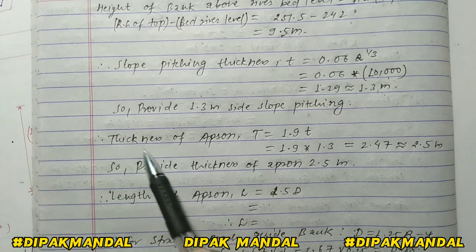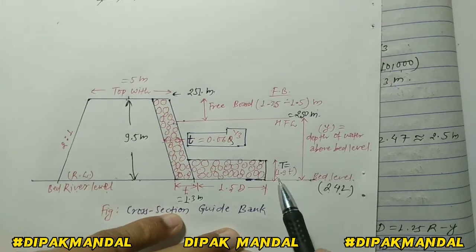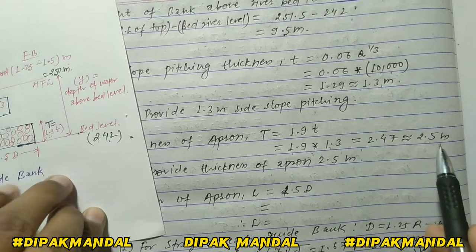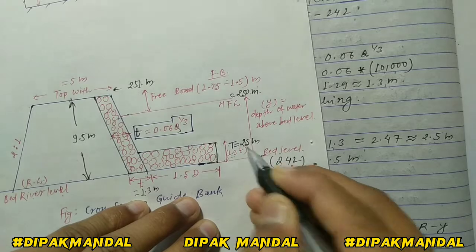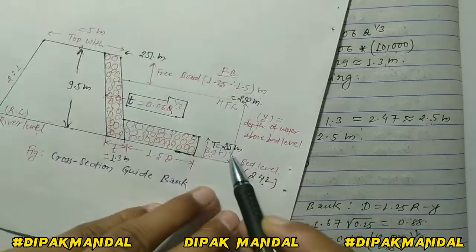Okay, now we have to calculate thickness of apron, that is the value of capital T, and this value can be calculated using this formula: 1.9 times t, and the value of t is taken 1.3. This value becomes 2.5 meter. So we have to provide capital T equal to 2.5 meter. Okay, you have to mention in this figure, and so provide thickness of apron equal to 2.5 meter.